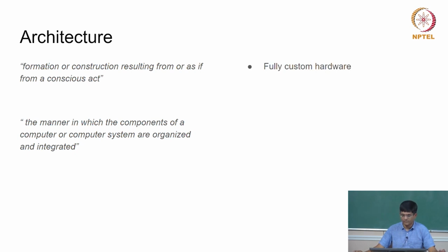At one end, which is what we would study if we were looking at it purely from the point of view of a VLSI designer, you would have something called fully custom designed hardware. Every adder, every multiplier, every register that is required for your design, you would decide it and decide exactly how big it should be and place them over there and connect them together. Obviously very difficult to do, but probably the best if you want to get the highest performance out of your system.